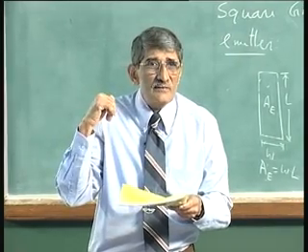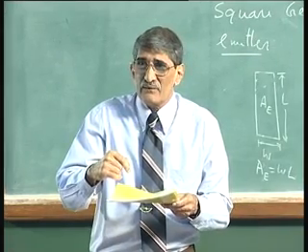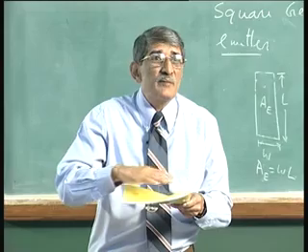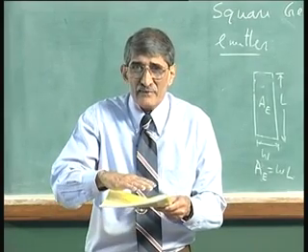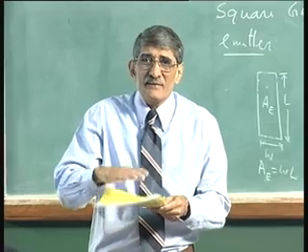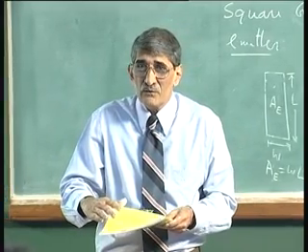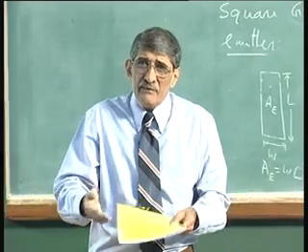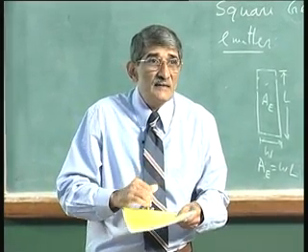When you grow silicon dioxide, it is a native oxide. Silicon is converted into silicon dioxide, so those dangling bonds are wiped out because of the SiO2. Here, if you deposit, it is just lying on top, the silicon nitride layer. You are happy, you put a cap and measure the beta, still not good. Even if it is good, it is not so stable, because the dangling bonds are still there.